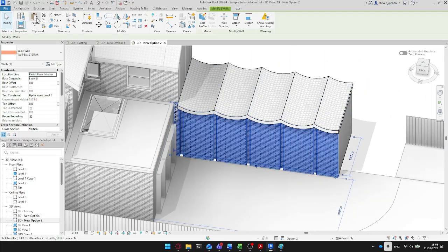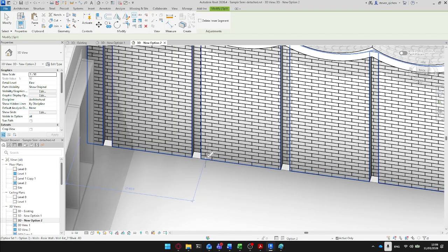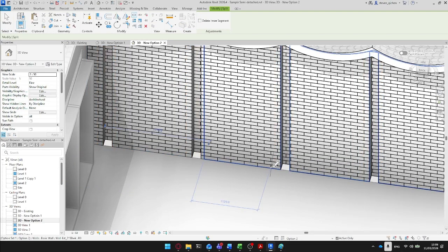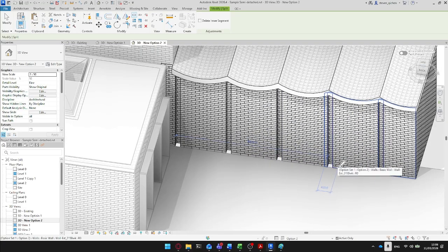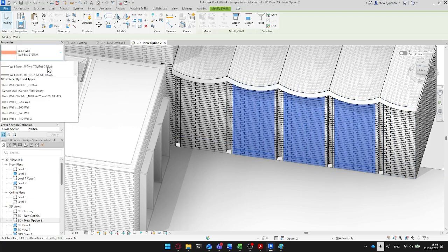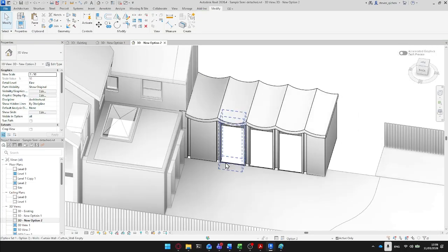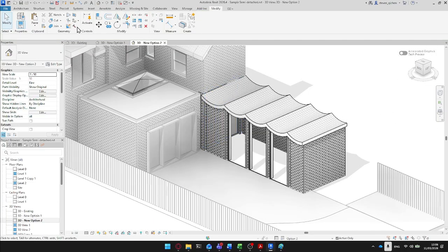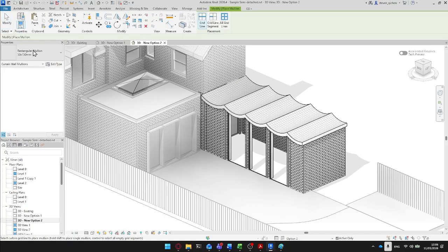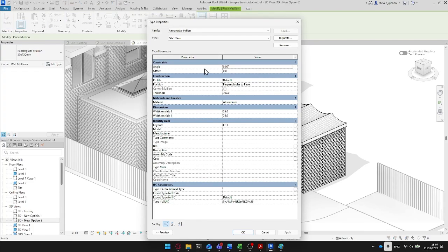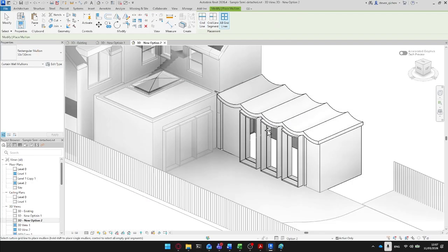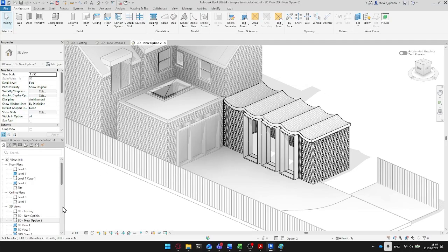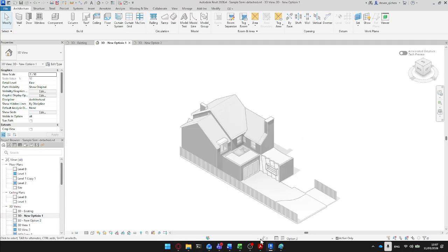I mean, just for simplicity's sake, I'm going to set some of this wall to be curtain walls for our windows. So I'm just cutting out a few sections of the walls that we're going to make into curtain walls. And again, we'll just add the same window reveal to them. So what we have then is your two design options.